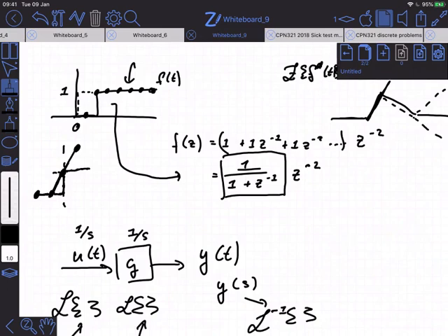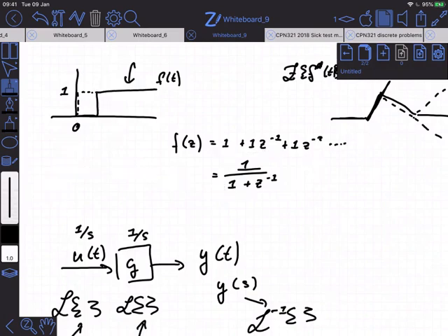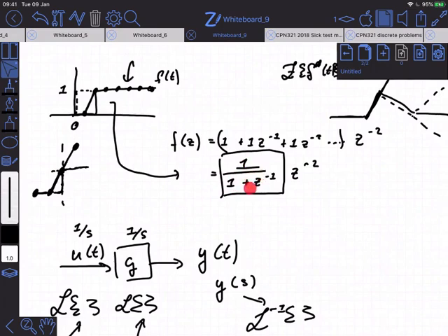I could have said, you know what, I'm going to encode that as a ramp. I could have done that. And I would have gotten exactly the same coefficients out. But the building blocks would be different. Instead of the step transfer function that I have here, I would have a ramp transfer function starting one time step earlier, and another ramp transfer function going down to cancel that one out. And so you can imagine that the math must work out such that if I actually work out the final result, I'll get exactly the same coefficients out.